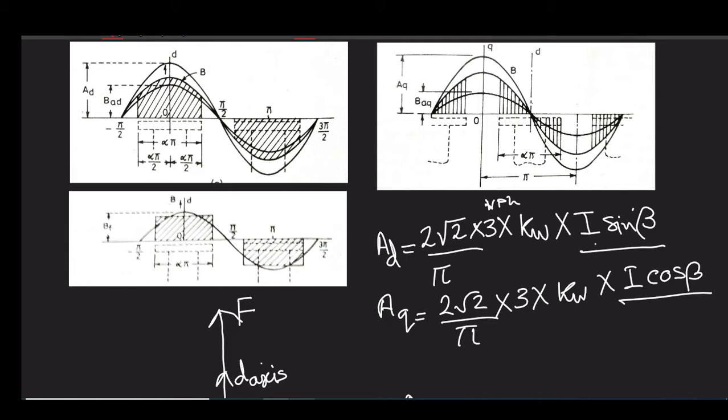If you try to represent them by reactance in the electrical equivalent circuit, then you should have two different reactance representations for them. Basically, in a single sentence, you need two different armature reaction reactances to represent them, and that is why it is known as Blondel two-reaction theory.